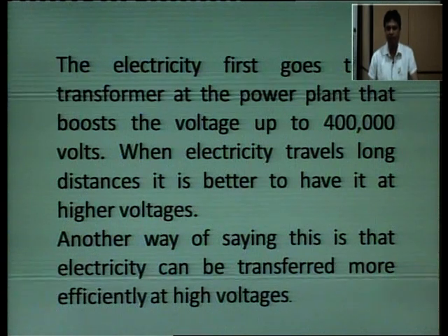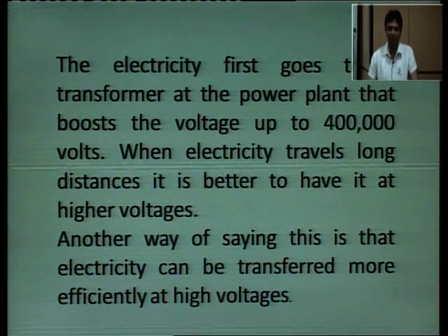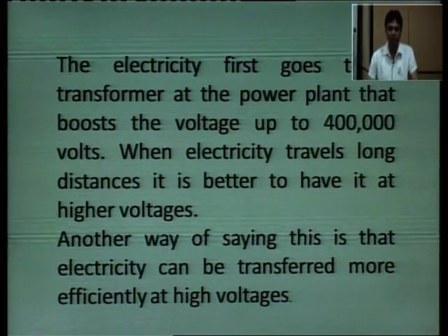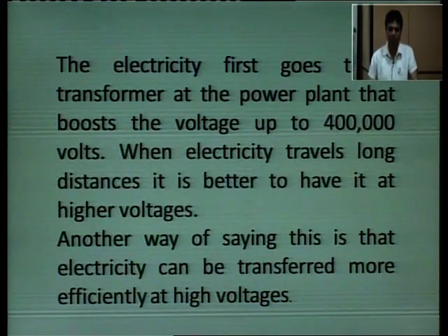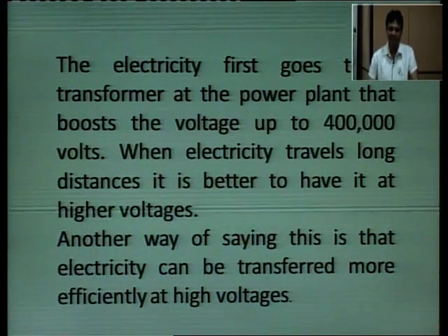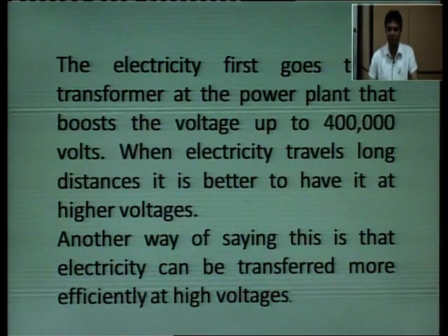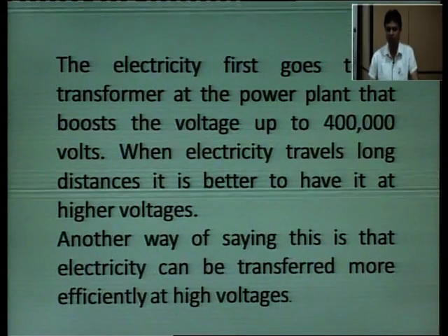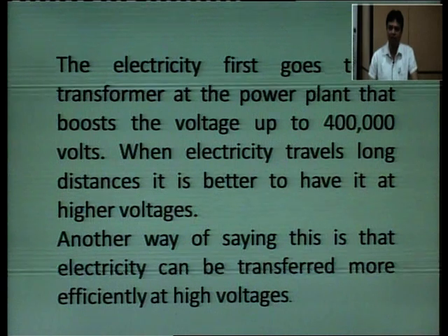Viewers, the question arises why we step up the voltage to such a high extent, meaning 4 lakh volts or 400 kV. The reason is that electricity can be transferred more efficiently at higher voltages. That is why we step up the voltage to a high extent.